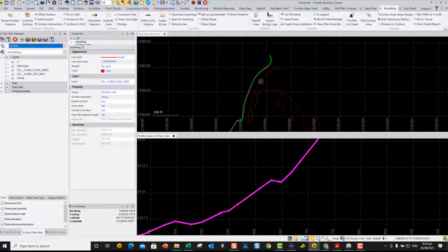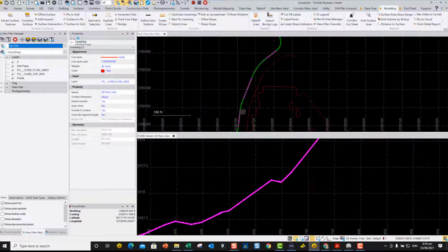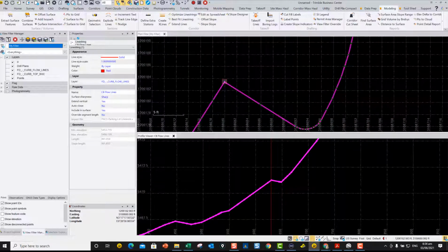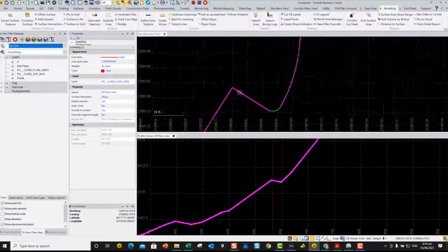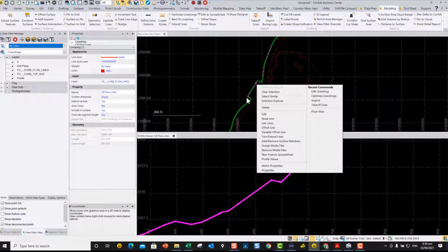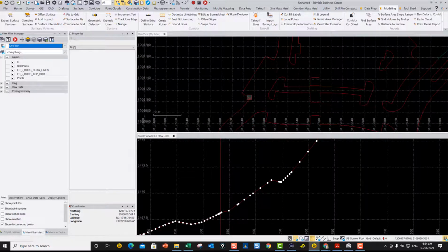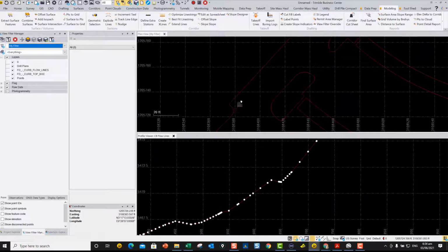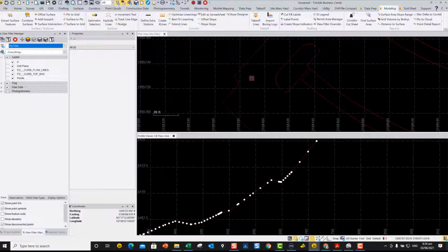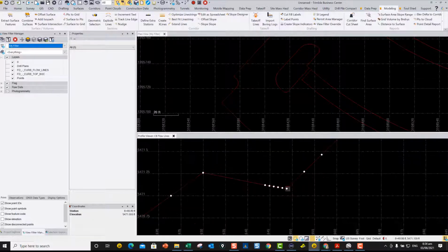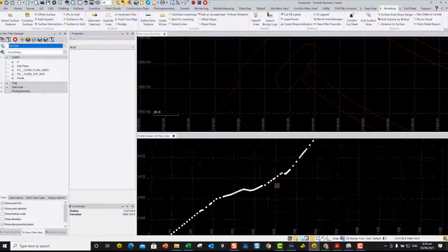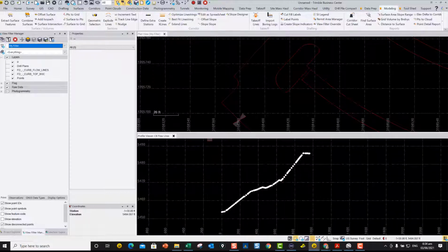Now when you're looking at curb lines like this, a curb and gutter machine could pave this line all the way down to here, even around this curved corner, but when it gets to this corner it would have to stop. This is a sharp break that it has to stop at. Then when it keeps going down through here, it would stop again at this location, and then it would pave this last piece all the way down to the bottom of the parking lot until you get to this right angle. Then it would pave around this corner as a separate line. So each of these lines has to be broken up, and you can see in each case, even though this is a curve, it's not fitted as a curve, so you're going to end up with a non-curvilinear vertical profile in the curb and gutter that you would pave with this line.